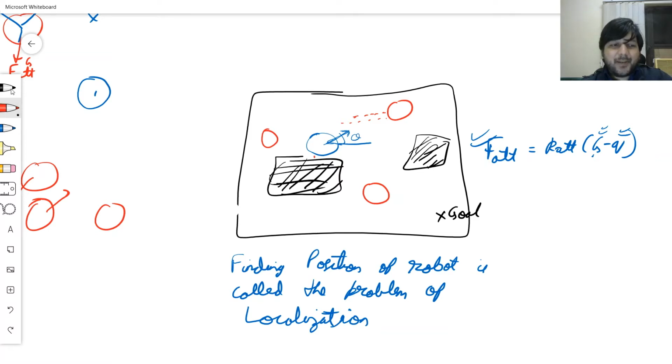And with respect to the robot, this is my laser ray, at a direction of alpha, and it strikes this, and I know this d alpha, which is the distance reported by a laser ray at an angle of alpha. The laser ray will go all 360 degrees. The back of it is not useful because it will detect the robot itself, so that's completely useless for me.